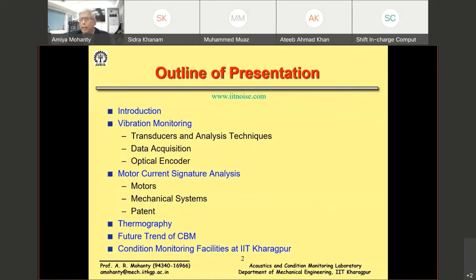Depending on the heat intensity, coming from the Stefan-Boltzmann law, at that area you can know the absolute temperature to the power 4 of the body from which these infrared rays are being emitted, and then we can find out the heat source or the temperature at any remote location.